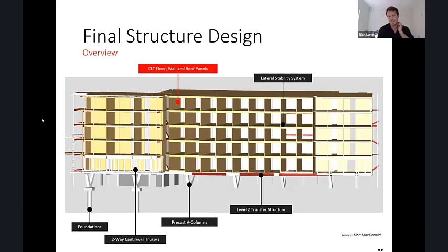We still had to keep a bit of steel in the premium pod areas where we had to retain those cantilevered zones. We just couldn't get the stiffness without the steel, but the advantage of the CLT is they were able to CNC it and fabricate it to a high level of tolerance that enabled us to place those panels in and around that steelwork with relative ease.